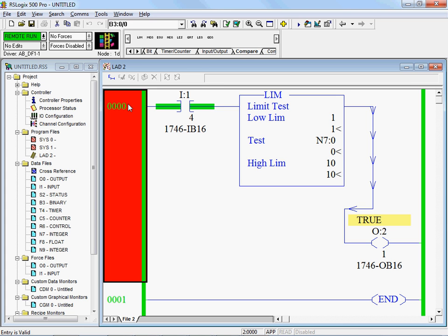is higher than the high limit, the instruction works backwards. We test outside of a range. If the low limit is higher than the high limit, then we're going to work backwards and test outside that range. If the low limit is lower than the high limit, we're going to test inside that range. I'm sorry? So you just flip it then basically? Yeah.